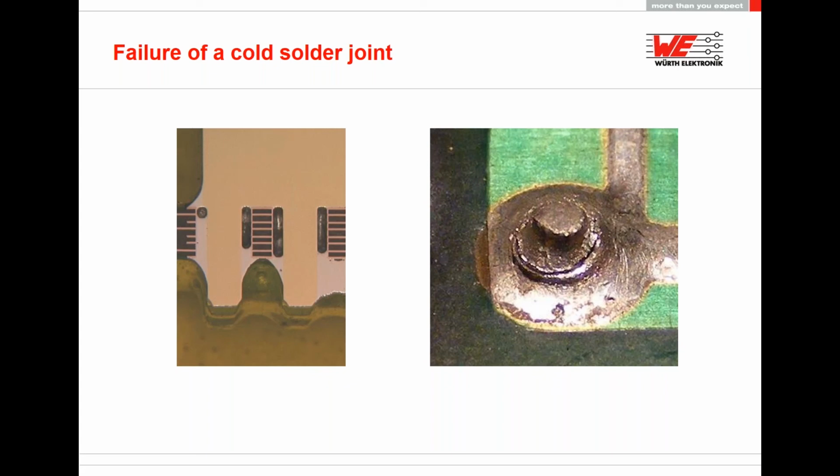And then out of this cross section, you can also take a look at the cable lugs, and for 16 square millimeters, usual cable lugs are like M5 or M6, and out of this thread size, you can take a look at the components itself and check the current specifications, and then choose the right part. That would be my suggestion.